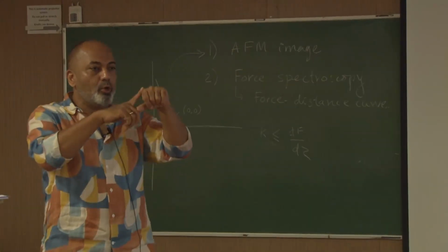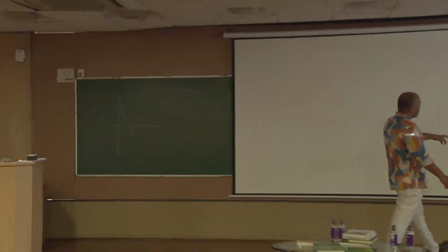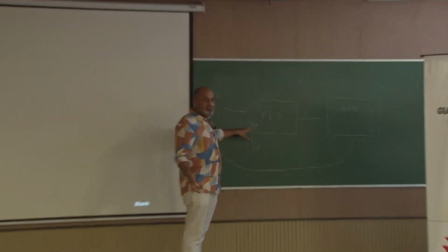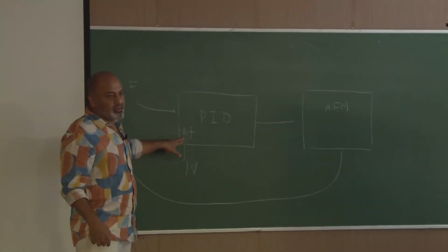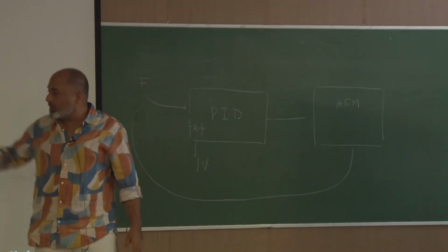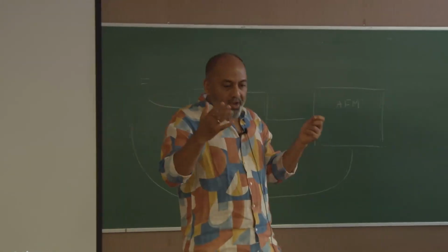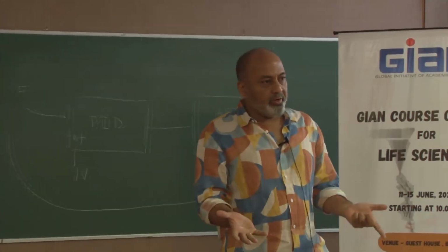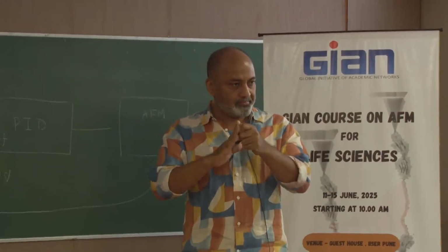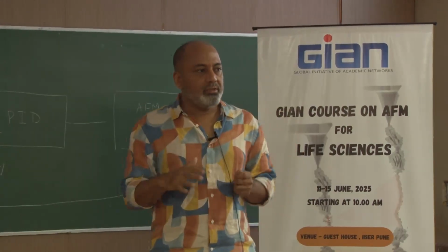So, once the cantilever is loaded, you can always change the PID reference here. This reference can be either 1 volt or 0.1 volt. If I put 1 volt, 1 Newton; 0.1, 100 piconewtons. So, if it is 100 piconewtons, along that curve you will either be on this side or that side, more load or less load. So, when approached and locked into feedback, I can change the reference value to push and pull, and at whatever value you want to take the image is your choice.